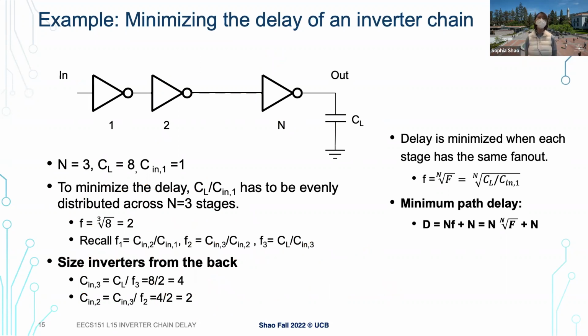You see why we want a simplified expression, so that we can reason about the trade-off and group them together. We can minimize the delay, and what we are modulating is the size of the transistor. We can size the transistors in a balanced fashion, then we get a good delay across the entire path.